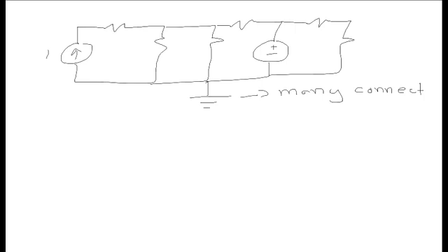In this particular case, that's going to simplify things. The next question I have to ask myself is, which nodes do I really need to consider as unknowns? If this is a 10 volt source, then I already know what that node is. It's 10 volts with respect to my reference. Because we've figured out the voltages here and here, I know the voltage of that node. I don't need to consider it. If you're wondering, it was 5 volts.